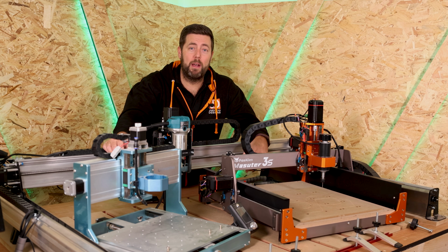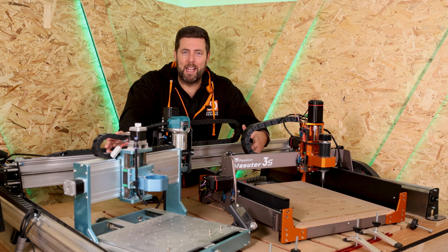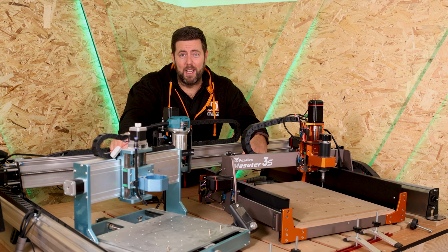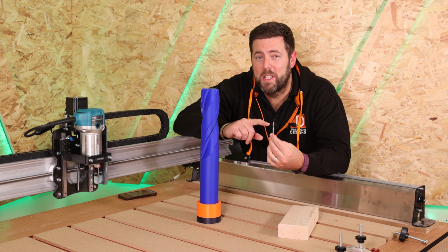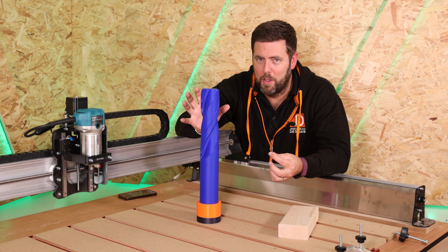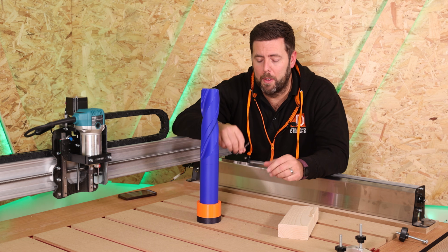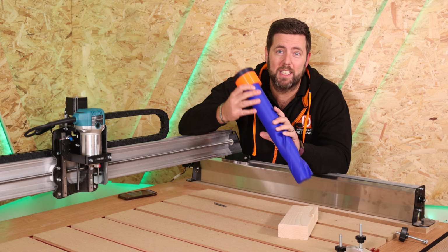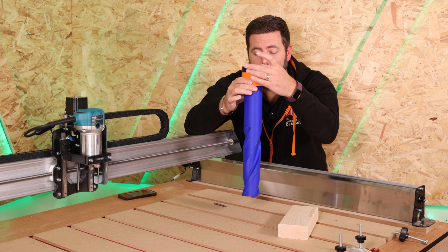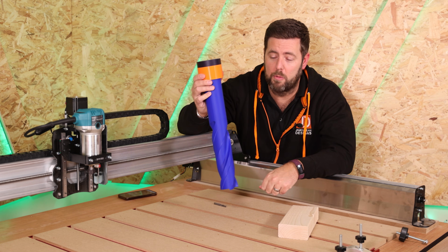Now, the next thing we're about to talk about is the bits themselves, and something you may have heard of called chip load. Don't worry, when most people talk about chip loads, they get into doing calculations. We are not going to do a single calculation today. So let's talk about my big blue tool. Here I have a 2-flute upcut end mill, and this is basically just a magnified version of that to try and highlight some of the things about the bits and the way we get to this thing called a chip load. In its simplest terms, the chip load is however much material is being excavated or removed by your bit when it spins and cuts through the material. Effectively, how much it is scooping away each time it does a rotation.